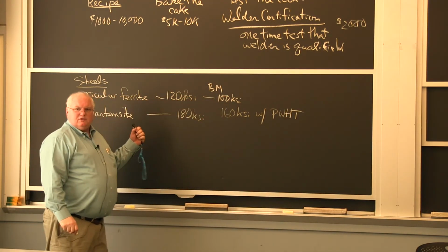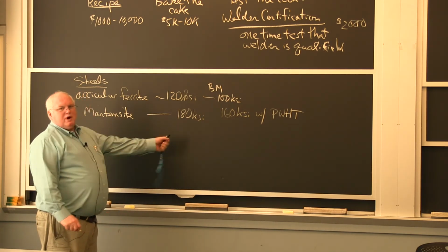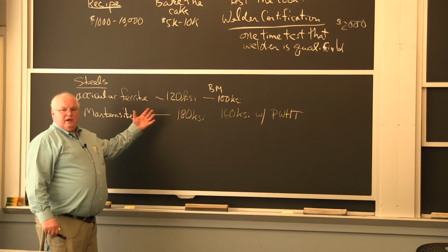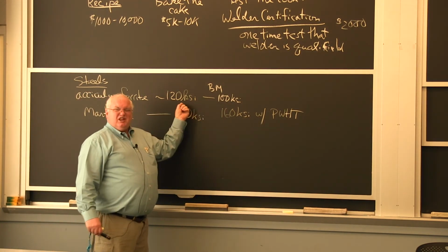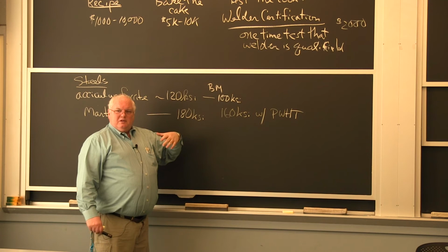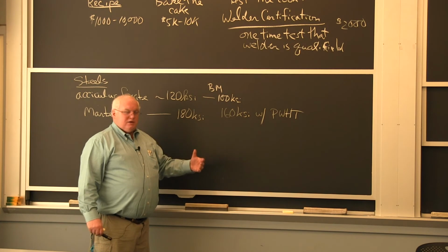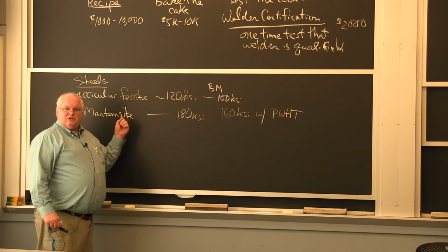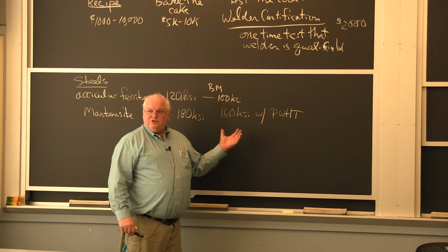And you're not Navy folks, but this summer when the Navy guys have to watch some of these lectures, that's what happened to the Seawolf submarine. Seawolf submarine was supposed to be welding HY 100 KSI, but they had a weld metal that was a little too rich in chemistry, had too much, they said, high side chemistry. The carbon was at the maximum of the range. The manganese was the maximum of the range. The chromium, everything was the maximum of the range, and they were getting 130 KSI weld metal. It was more of a martensitic rather than acicular ferrite, and all of a sudden they ran into all kinds of problems with hydrogen cracking.